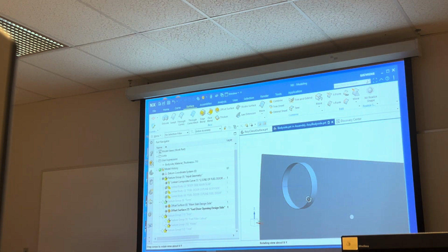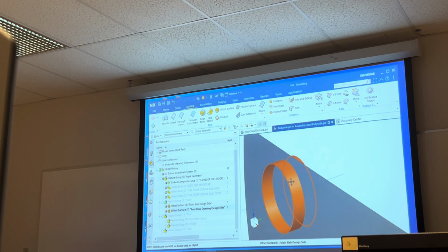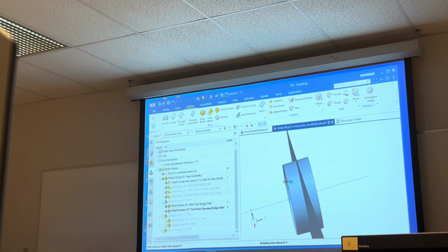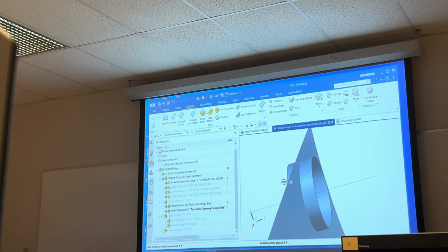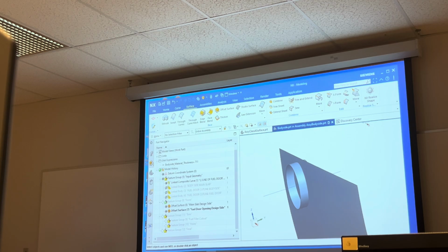It's gonna seem odd as you do it. When it's all said and done, maybe you'll see exactly why, but it's just because it's important to make sure you're following the rules about the bend radius, right? So it's gotta be 3 times the material thickness. So, all right, let me do what I was gonna do and see if it makes sense now that I said that.